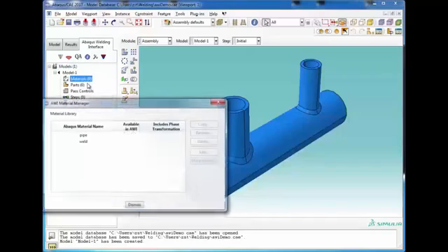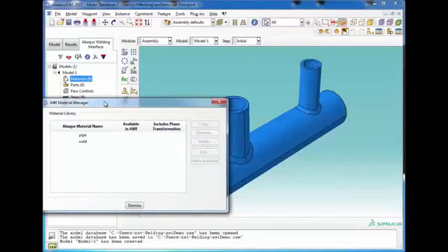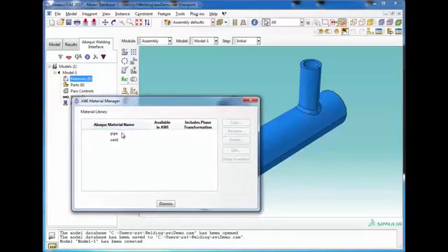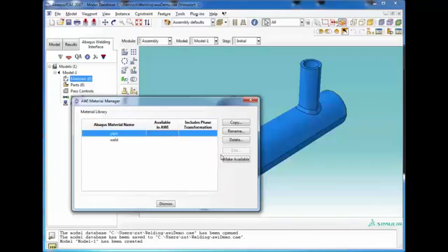This one, the manager. Okay, so the material manager displays which materials are available for the plugin to be able to use. At this point, it shows no materials are actually available to be used by the AWI. It shows that there are materials that have been created, but we can't use them yet in the AWI. The reason is that the material properties you would have created in Abaqus CAE, like the elastic, the plastic properties, thermal conductivity, and all of that, define just about everything we need. But we have to add one more thing essentially.